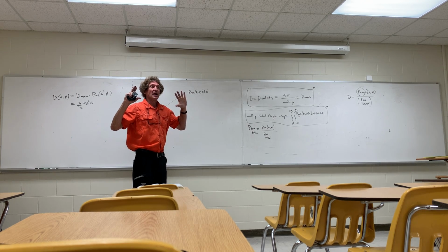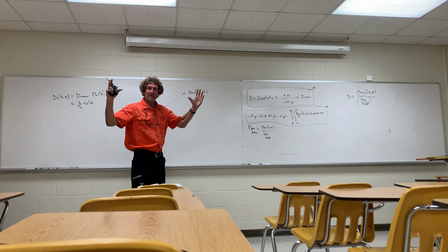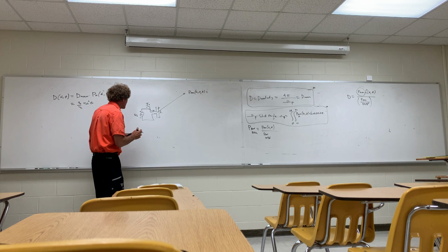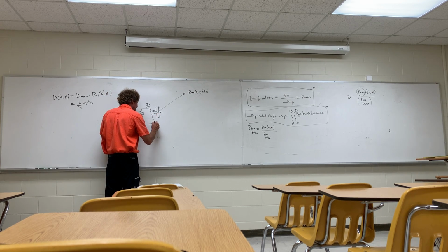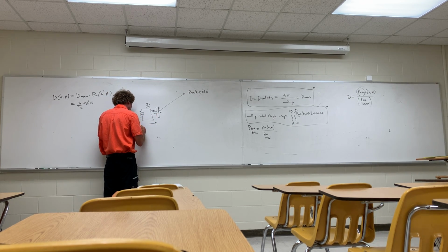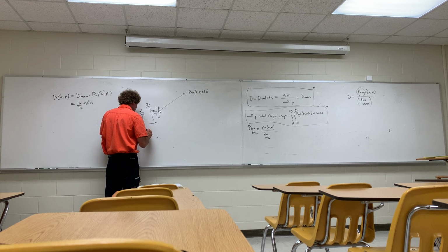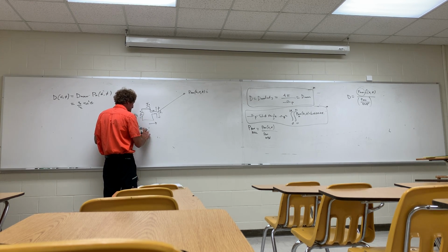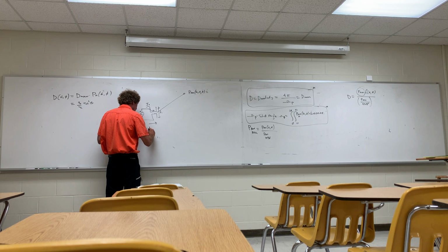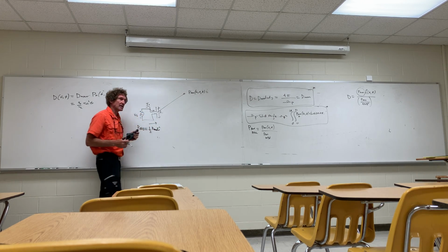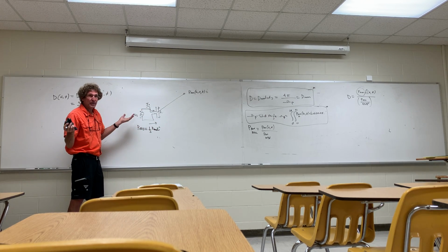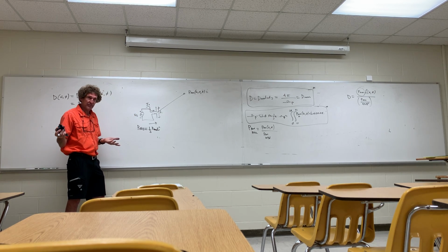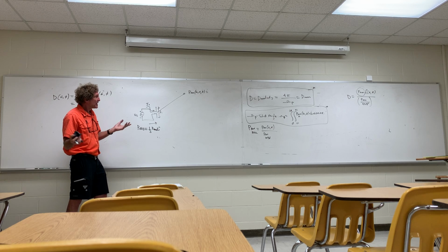You take the isotropic radiated power density. So I'm radiating P rad, which is equal to 1/2 times the radiation resistance times I naught squared. With me on that? If I have a short dipole, I know the radiation resistance. I can figure out the power radiated if I know the current.